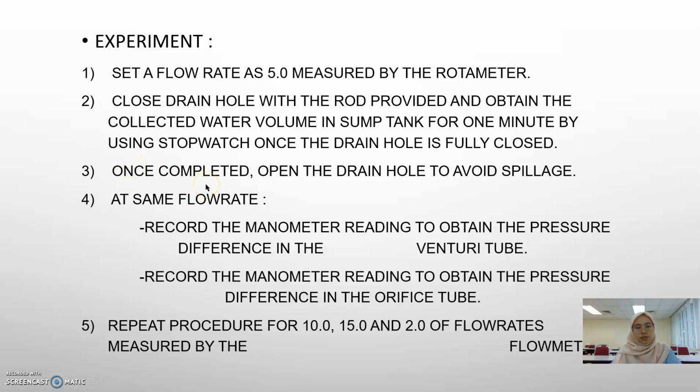Third, once completed, open the drain hole to avoid spillage. Fourth, at the same flow rate, you have to record the manometer reading to obtain the pressure difference in the venturi tube. And also you have to record the manometer reading to obtain the pressure difference in the orifice tube.